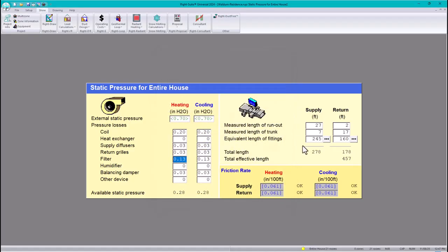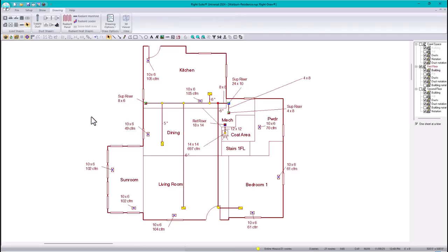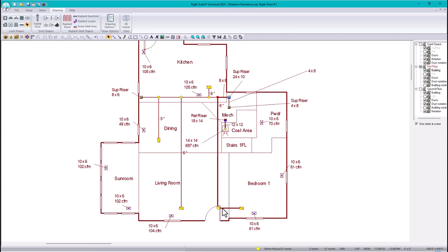So that's why I was changing it on paper. It could work, so technically you're gonna pass, right? It passed, but in the field it might not pass, right? In reality, you want to provide very good customer service, so you need to play with those numbers in the field, and the installation too. You can also find different ways to maybe reduce ductwork or something like that.